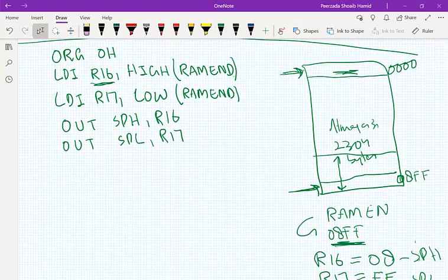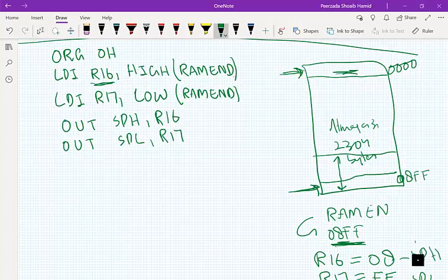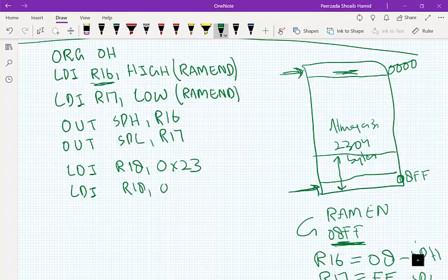RAM. So now I will write some instructions that will actually store data onto the stack. For example, first I will write some information on some registers. I write LDI R18, some information, maybe 0x23, LDI R19, 0xFA, LDI R20, 0x32, any data. I'm randomly writing any data onto the registers.